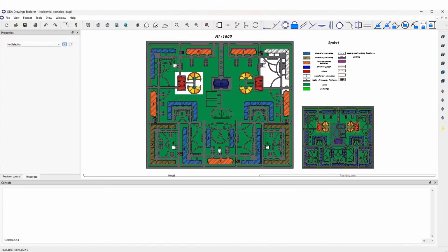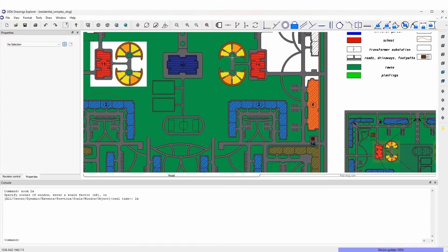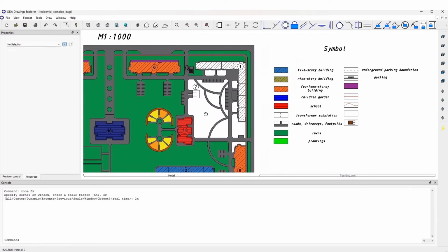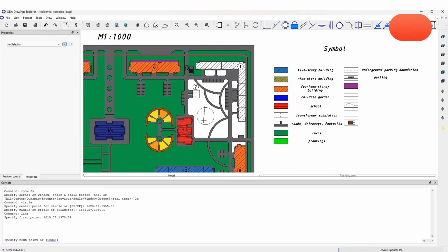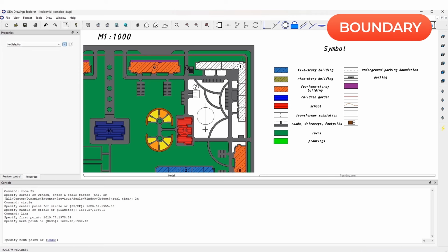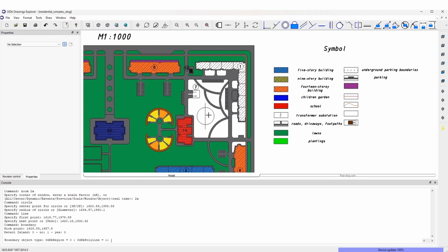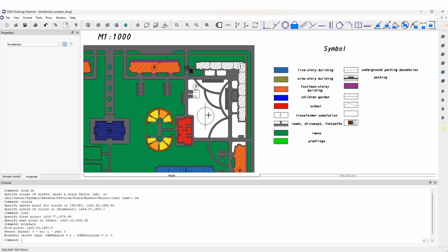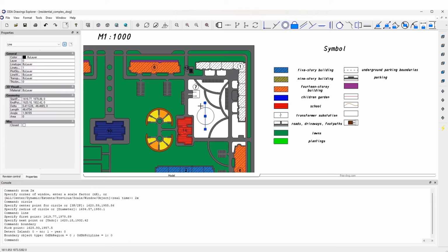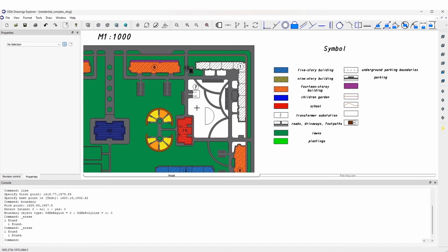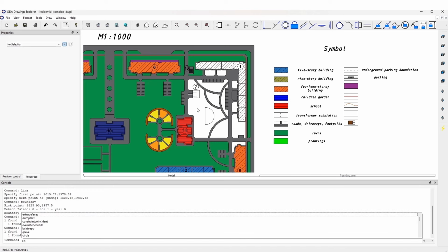If you have a 2D drawing, it is very likely to contain some hatches. Facilitating work with hatches is a key focal point, and we have made advancements in this area as well. For instance, we simplified hatch creation using boundary command functionality as a base. Just to remind, the boundary command allows you to create an entity with a closed loop from multiple entities in a specified area of a drawing.